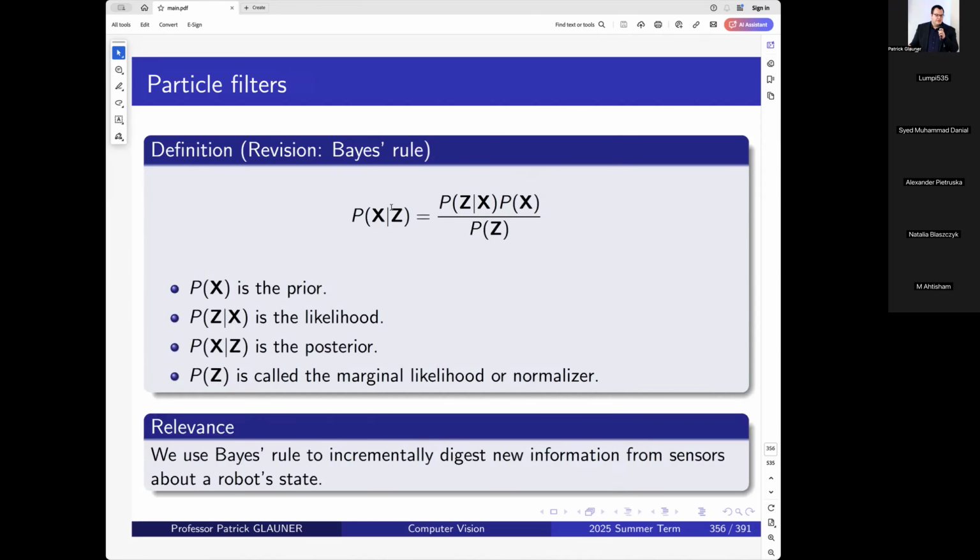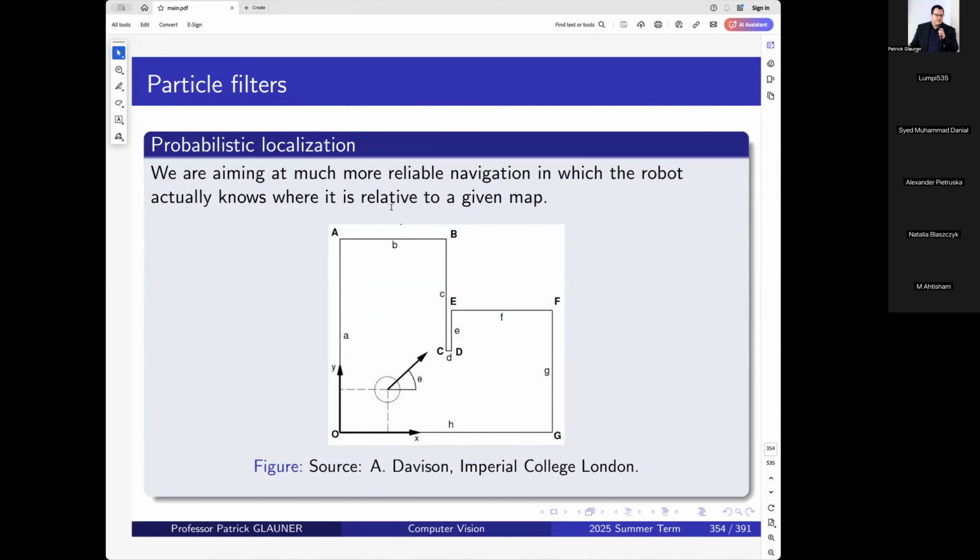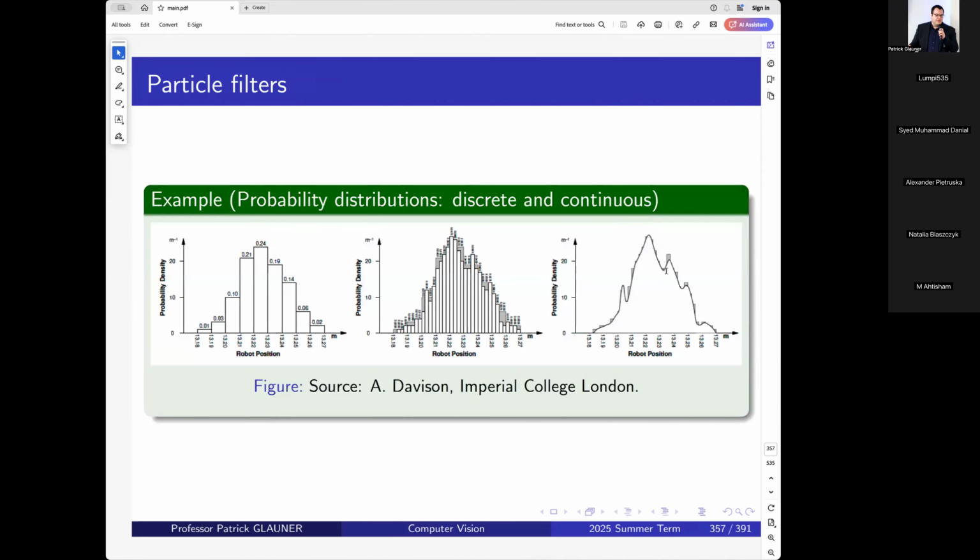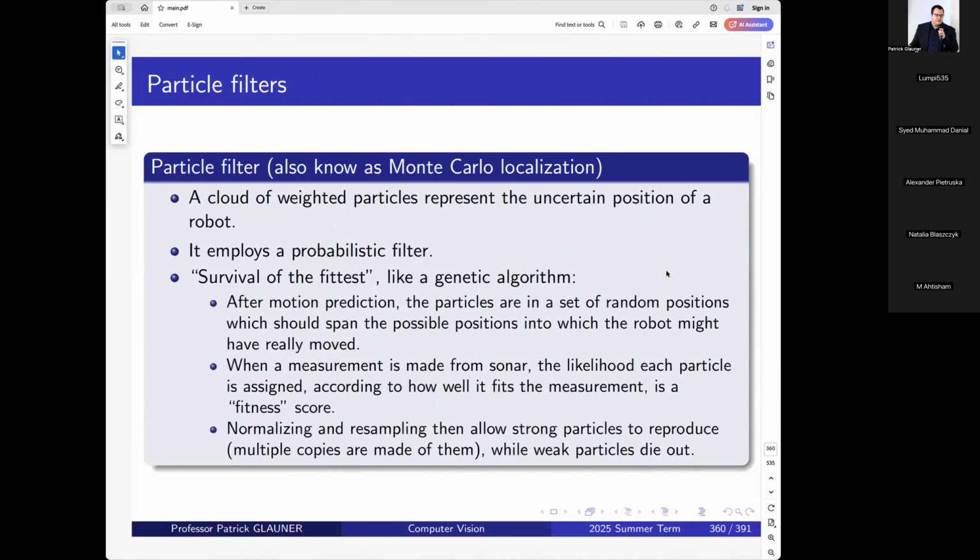And it's very important, a distance, because it's not necessarily this wall over here. Maybe some particles are rotated and they would look rather at this, or they are shifted up here and they would look up there. So we try to plug in this measurement information and then see which particles are most likely where the robot actually could be.